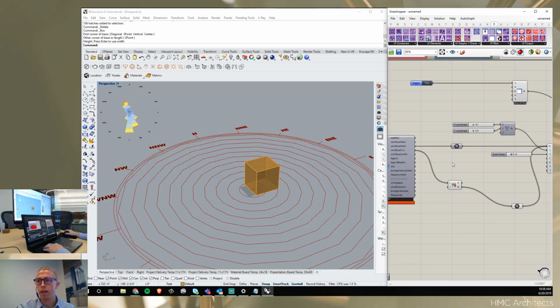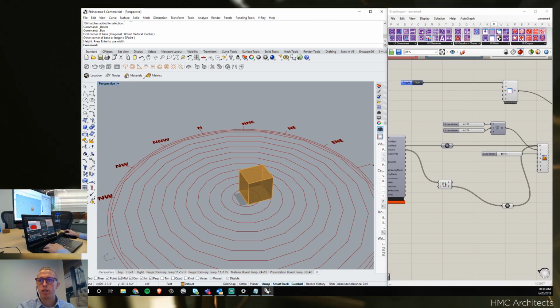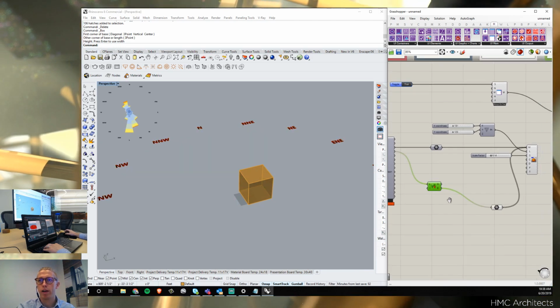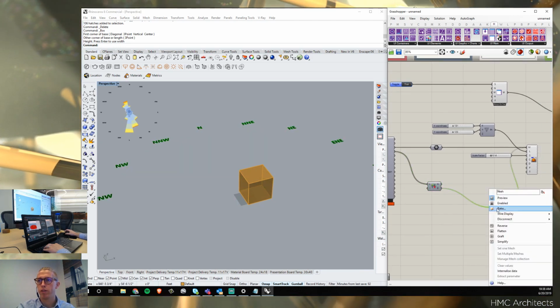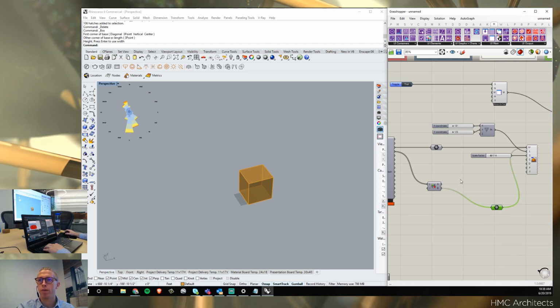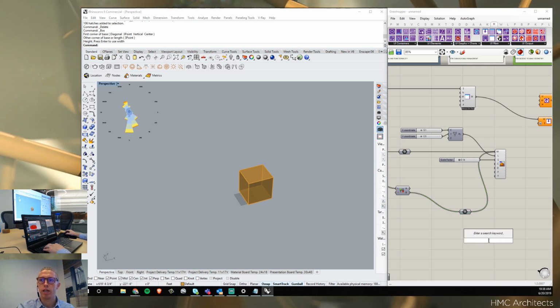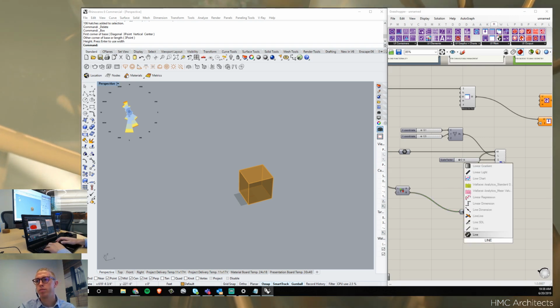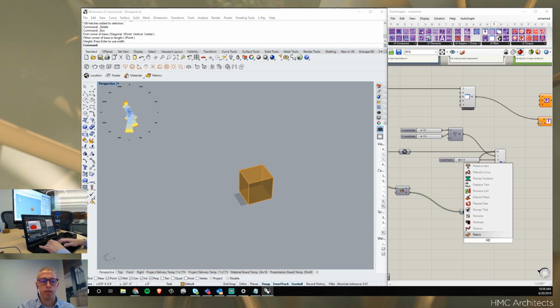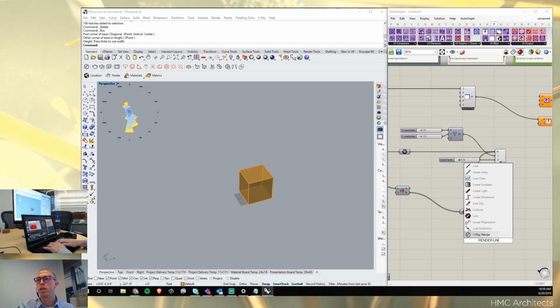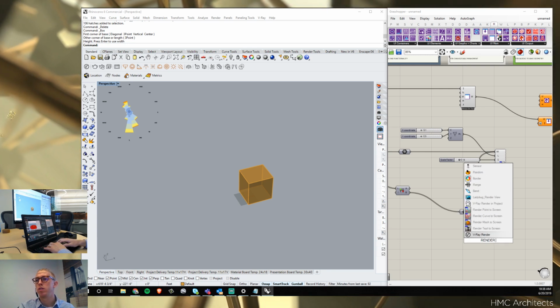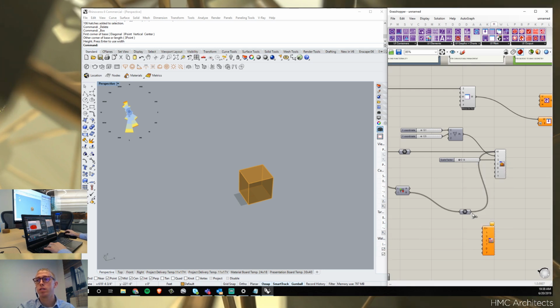I'm going to delete that component, and I'm going to preview that off, and also preview this off because I don't want to see those there. So now I'm going to try to project those lines up there. Render, I think. Render line. Render curve to screen. Let's see.